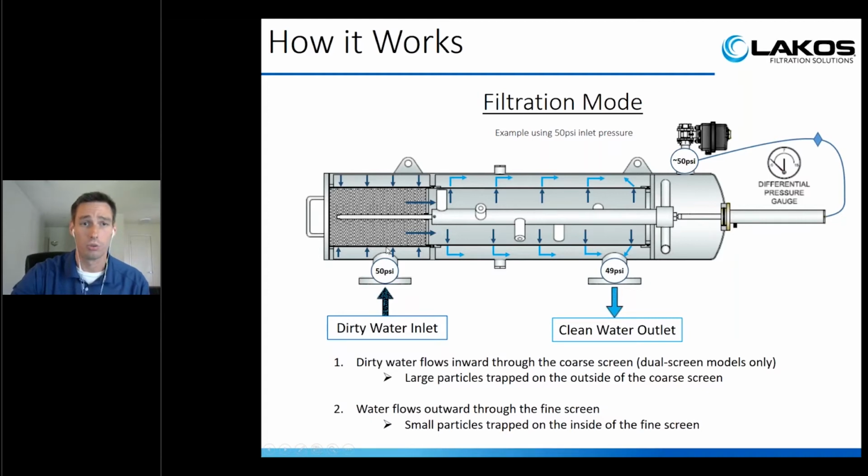The only way to clean the coarse screen filter is to remove this end cap, slide that out, clean it, and put it back in. But you really shouldn't have to be doing that very often. If you do, you've got some upstream filtration or supply issues that you may want to look into. This is really meant to just protect these spray nozzles on the inside from being exposed to too large of particles, otherwise they can get plugged. That's really what this is for.